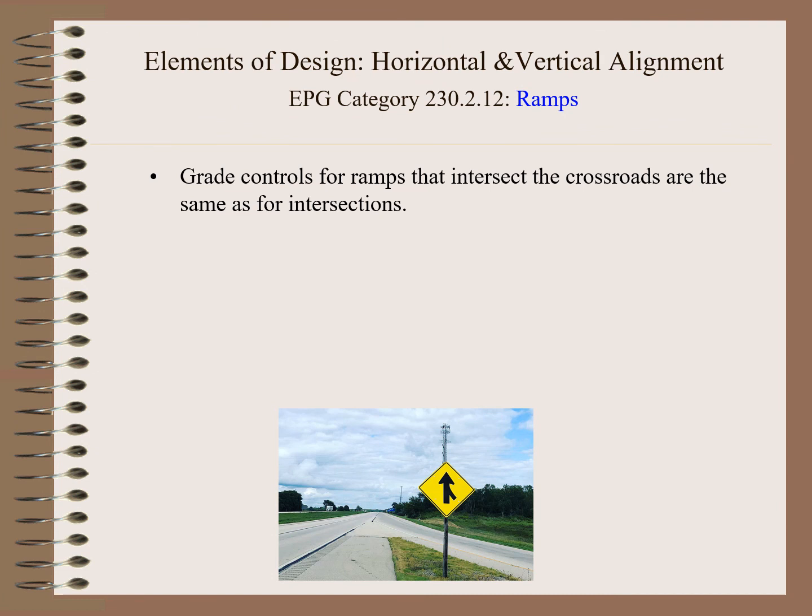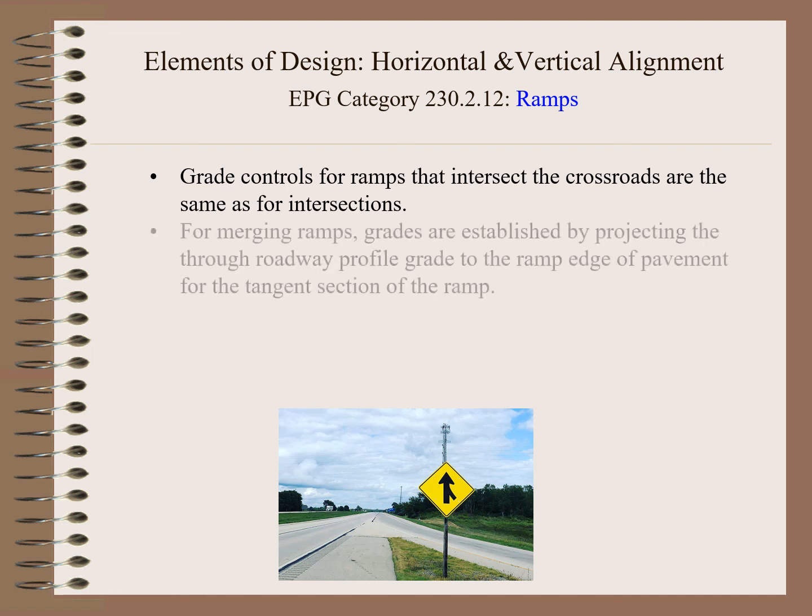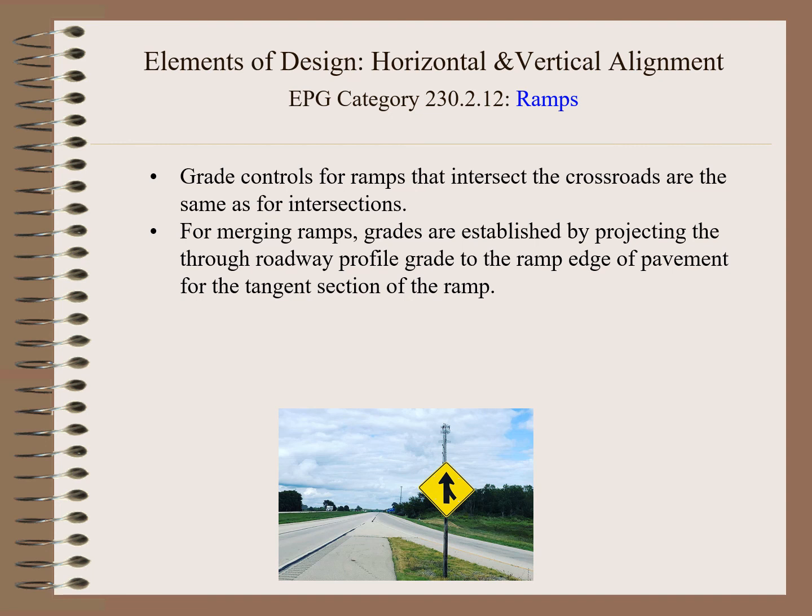Now we're going to talk a little bit about ramps. Grade controls for ramps that intersect the crossroads are the same for the intersection. For merging ramps, grades are established by projecting through the roadway profile grade to the ramp edge of pavement for the tangent section of the ramp.